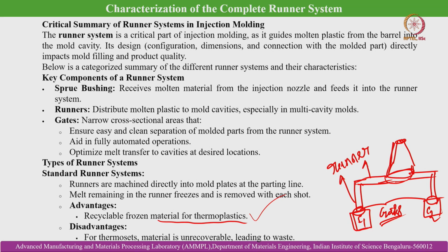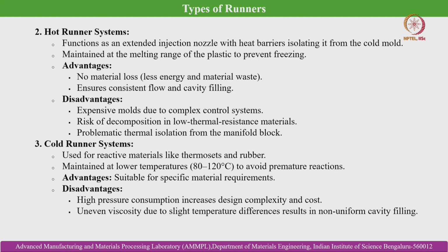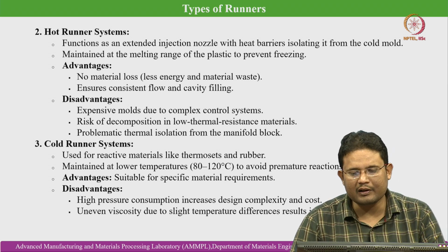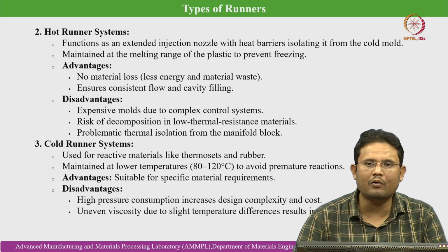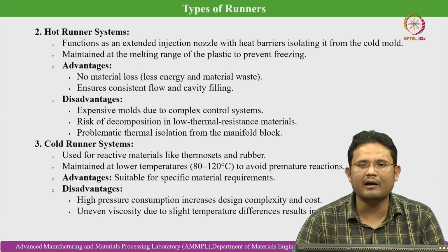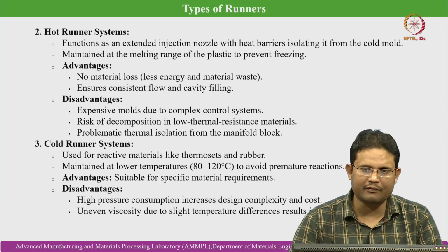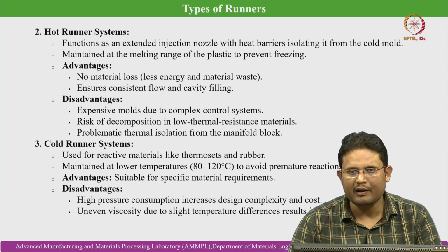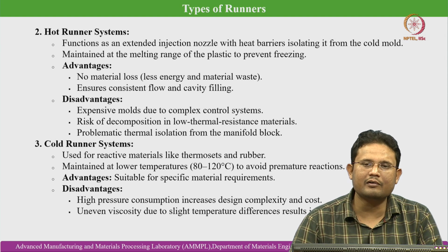That means the solidified material in the runner becomes waste. So, what is the remedy to that? The remedy can be to implement hot runner systems, which we will discuss next. A hot runner system functions as an extended injection nozzle with heat barriers isolating it from the cold mold. Basically, in the case of hot runner systems, the melt never solidifies, it always remains in a fluid state, and through this hot runner system it enters into the component cavity.